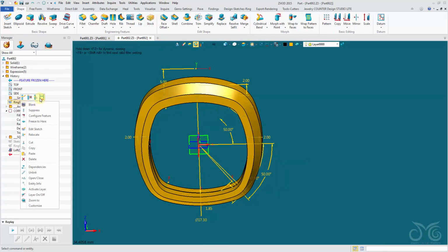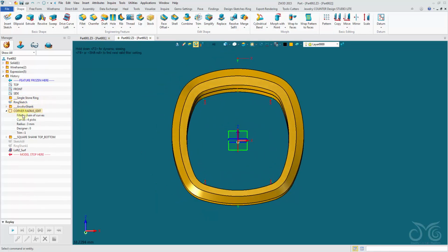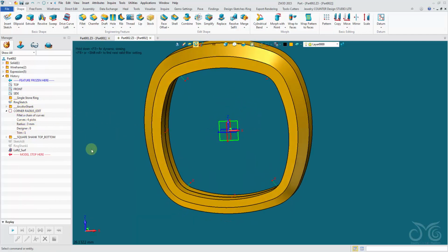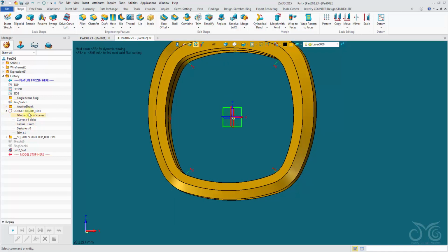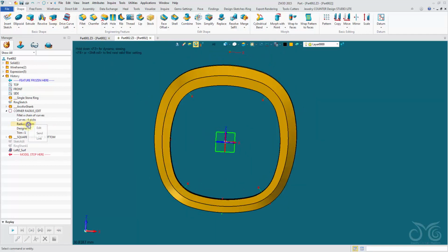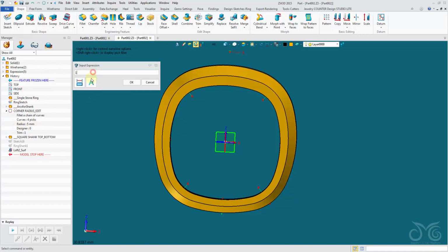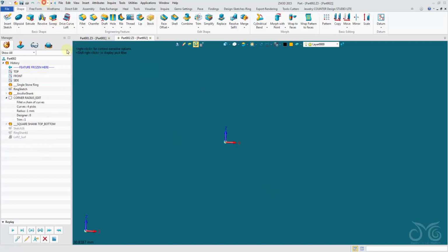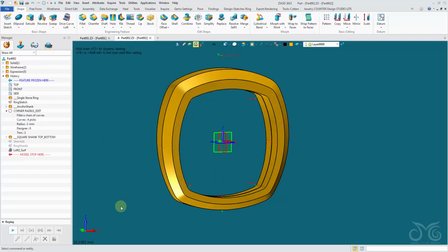Okay, let me turn off these dimensions here because we have one more thing in the history. This is our corner radius edit. Okay, we can make modifications to the radius of our corner. Within here, this is just a chain fillet in the template history. Let's say we change the radius to 5 millimeters. Regenerate. Okay, you can see it rounds off our edges more. How about we drop it down to 1? Smaller radius will have more abrupt edges there, and you can see the change.